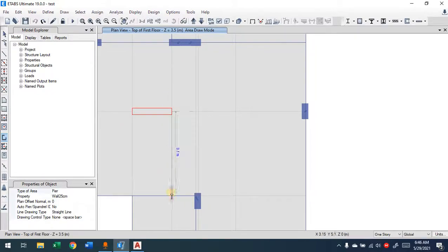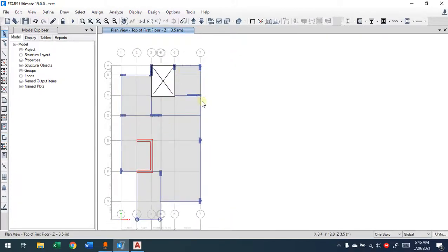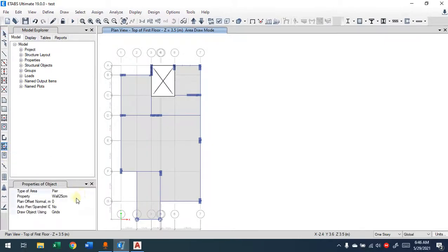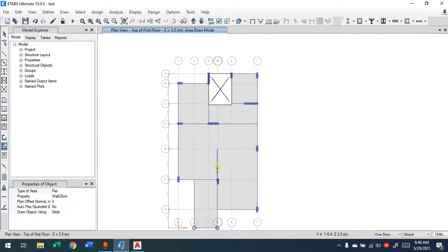But here I have beams everywhere. So normally when you're drawing a shear wall, you don't have beam over the shear wall. Let's say I'm placing it like this. Or you can place one at each corner. Some people do it a different way. This will be the shear wall that we have. Drawing it is very easy. Well, the quick draw wall, how does it work? Similar way, but this time it only goes for the grid line. So you're trying to provide it between two grid lines.